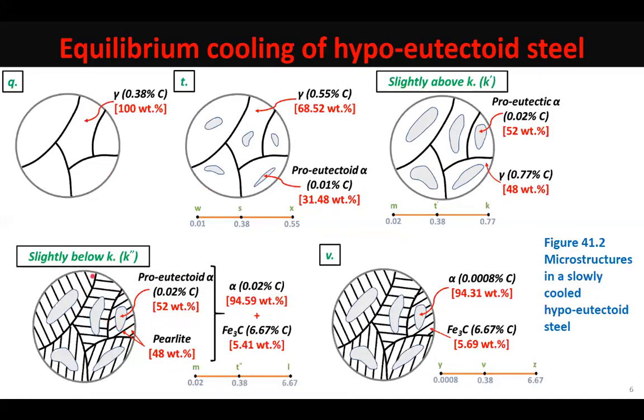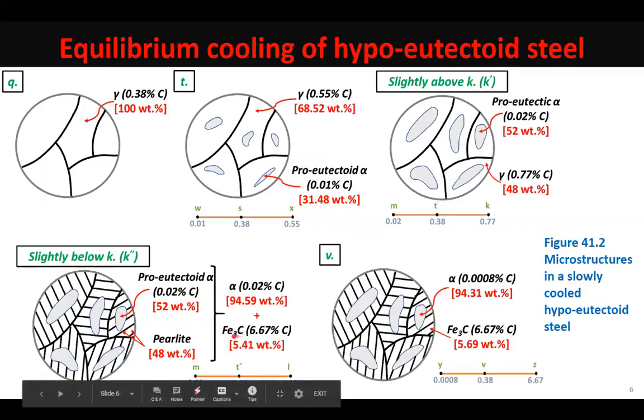One is this eutectoid ferrite, the other is this eutectoid cementite, and the third is this pro-eutectoid ferrite. But the phases are only two. The phases are ferrite and cementite. But specifically, you would say, sir, we have pearlite and pro-eutectoid ferrite in the microstructure, and you can even individually find out the total amount, because the difference is that the source of cementite is only one, the eutectoid reaction, but the source of ferrite has been two.